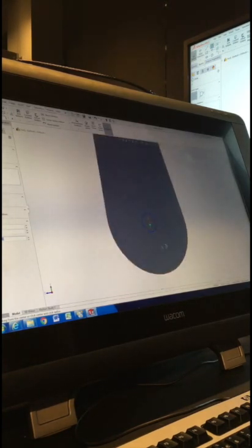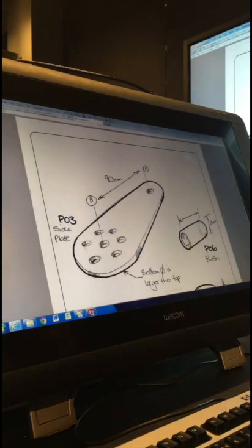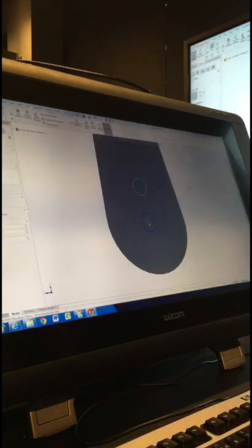I also want to do those holes at the bottom. So I'm just going to draw one circle here. Those holes at the bottom are all going to be the same size, and we're going to assume that they're going to be equal spacing. All right. So we're not going to draw 6 holes. We draw 1, and then we're going to pattern them. So I'll show you how to do that.